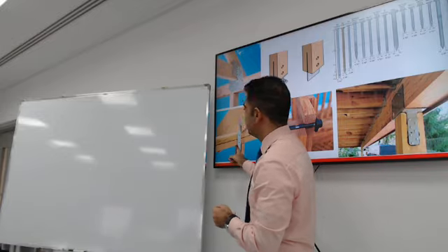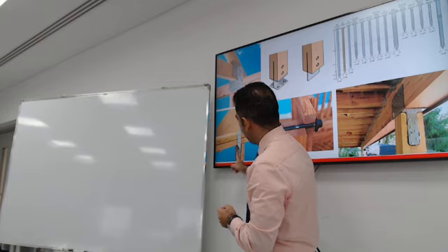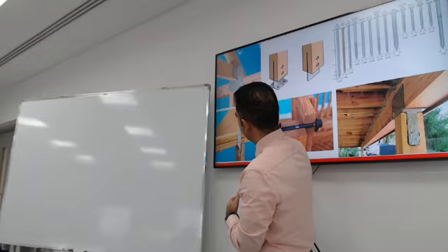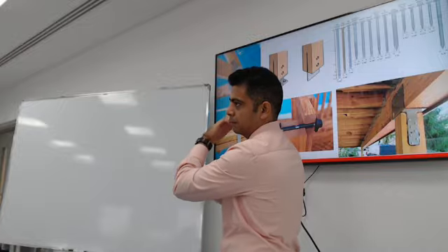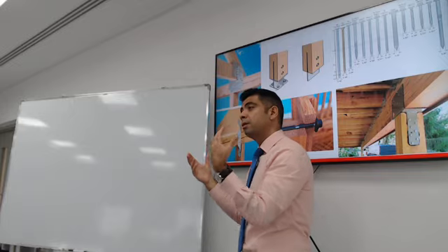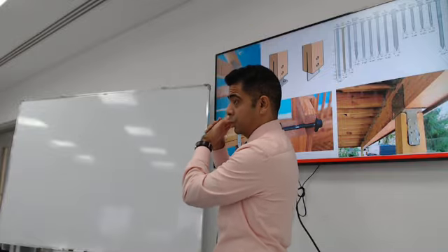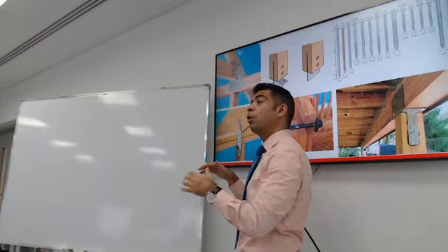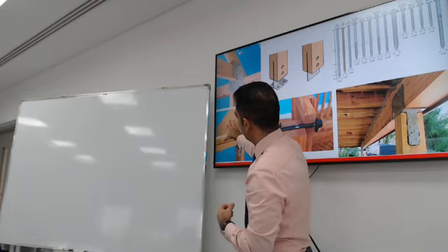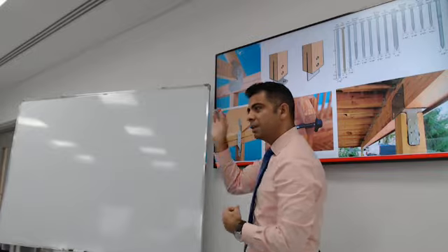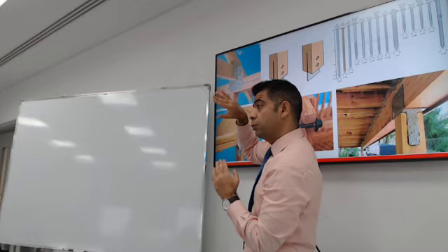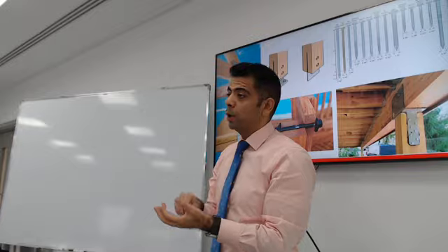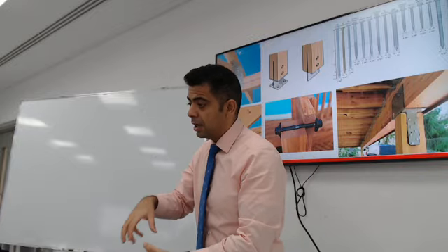I want to point you to this detail over here. This accessory, I know this is used a lot. This is called a hurricane tie. That's the actual name of the product from the manufacturer. This element here is part of the roof system. Typically, if you are in a cold environment, you might get snow loads. Snow loads are less if you slant the roof, so you can shed the snow load and not let it accumulate on the roof. If you want to tie the roof to the wall, you need these very thin steel ties to connect the roof to the walls or the rest of the building in case of a storm. Believe it or not, the effect of wind on the roofs is not actually compression, it's suction.